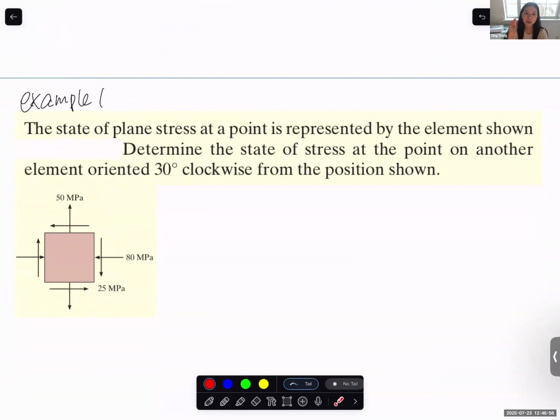Of course, tension and compression should be simple, because every time you see a compression, obviously this one should be a negative value when you plug into the equation, because this is a compressive stress. And when you plug this one into the equation, you know that this is a tensile stress, so you need to use positive. And the thing that gets more complicated is shear.